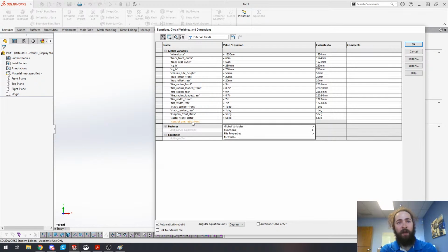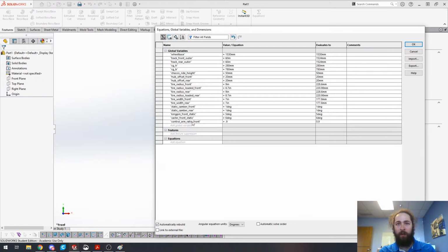You can either define both of the front, like for example, the length of the lower control arm and the upper control arm, separately, or you can define them based off of a ratio. The ratio of the lengths of the control arms is what affects your camber gain in cornering. So I like to set that up front, and then just say, hey, my top one is going to be 90% of the length of my bottom control arm.